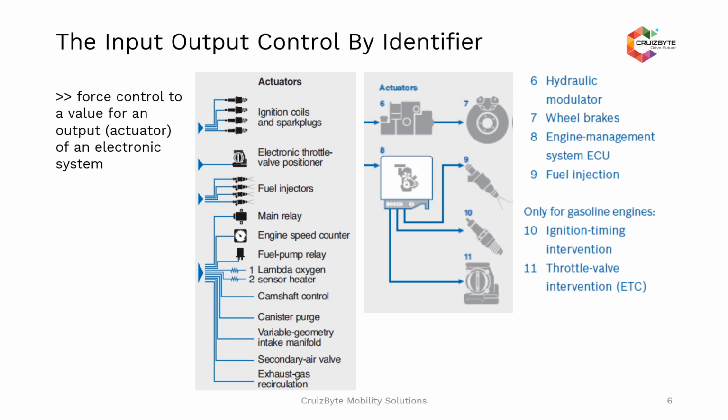With some specific parameter value, we should be in a position to override the function from the ECU server, and the diagnostic tester takes over the control of this component momentarily, and we call it a short-term adjustment.